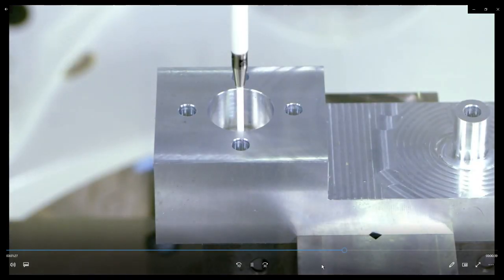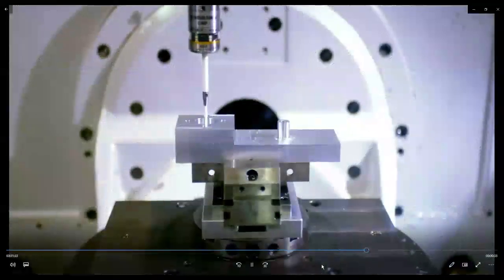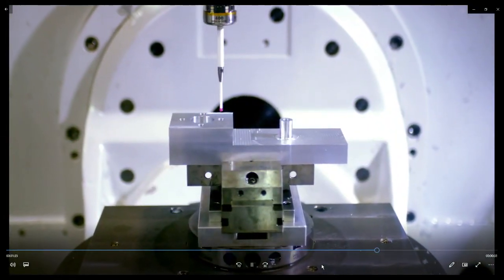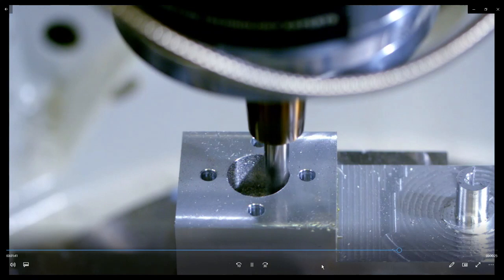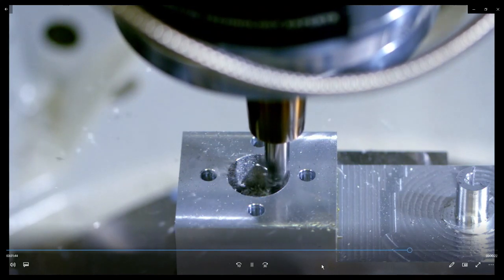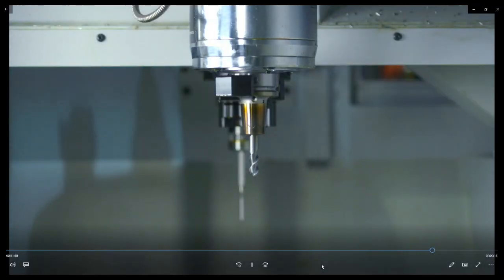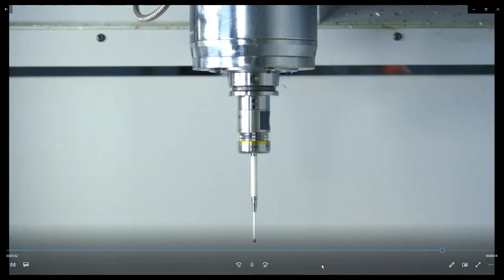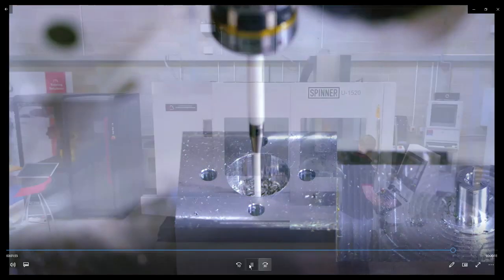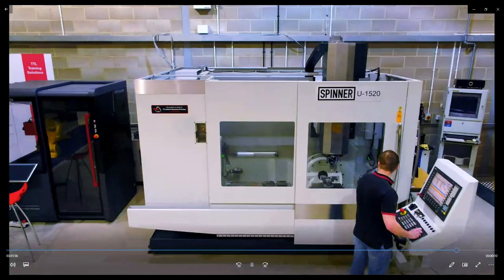The Probing Plus add-on for Siemens NX enables further control of the manufacturing process from within the CAM environment. By allowing the offline programmer to integrate probing cycles and validation of the machine part seamlessly during the machining process, the programmer can add probing checks in line with machining operations to ensure the final cut is accurate and to specification. Key benefits are greatly reduced scrap rate, more consistency to finished components, and minimal manual input and chance for error. If for any reason the part has been set up on the machine incorrectly, the cut-measure-cut nature of Probing Plus can prevent pointless machining of a component that may already be scrapped by measuring features and verifying whether they are in tolerance prior to finished machining.